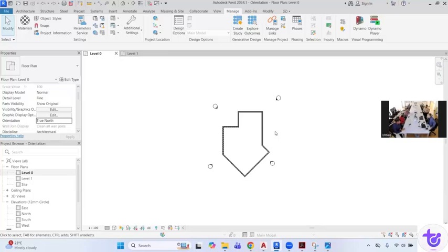In case two software are not having the same compatibility, for example, we cannot directly import or link the Rhino or Grasshopper or some other software's geometry into Revit and vice versa. So there is a common bridge file, the IFC format, and then you can transfer it to the other software. Yeah, that's the actual use of the IFC.